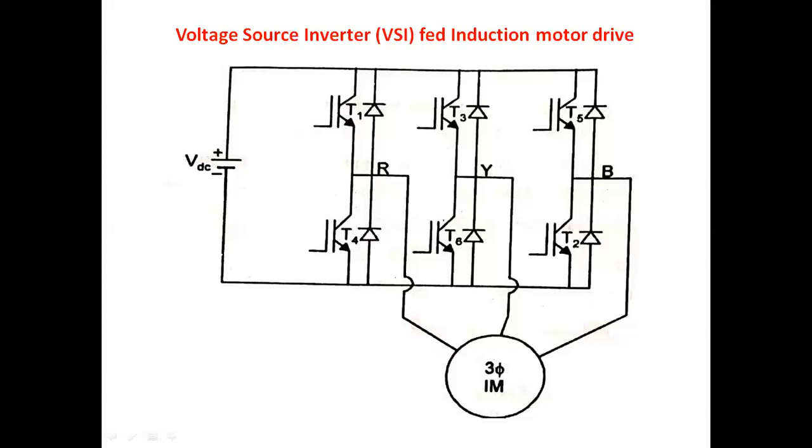Then what is the difference between these two inverters, the stepped wave inverter and the pulse width modulated inverter? You must remember this, listen carefully. A stepped wave inverter has the possibility to control its frequency internally. That means it only controls the frequency; it cannot control any voltage or current magnitudes inside the inverter. So if you want to regulate the voltage and current quantities, you need external means. External voltage control and external current control are required for a stepped wave inverter.